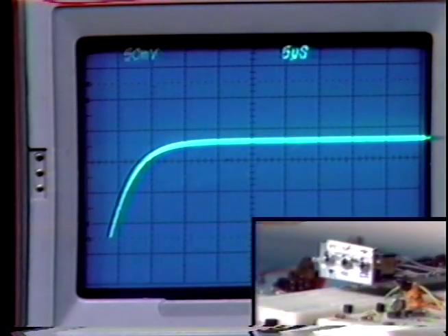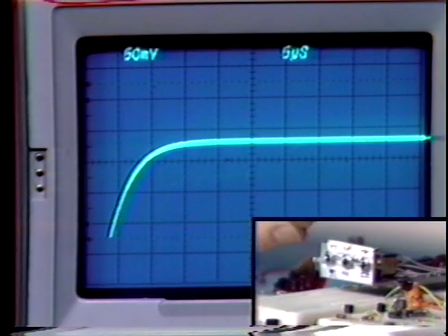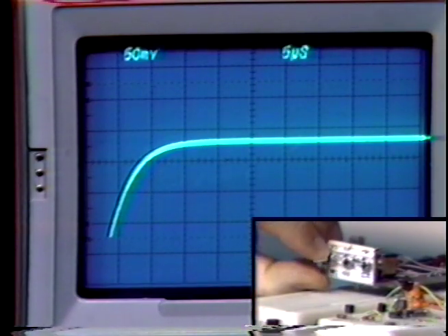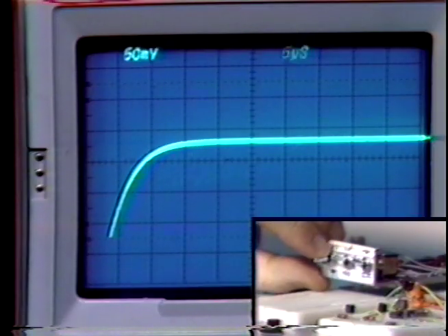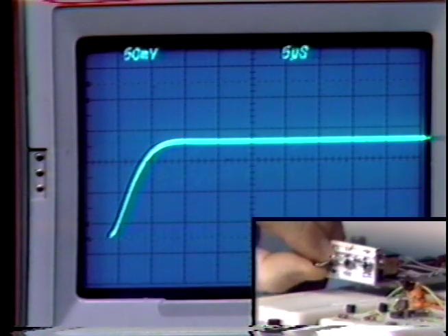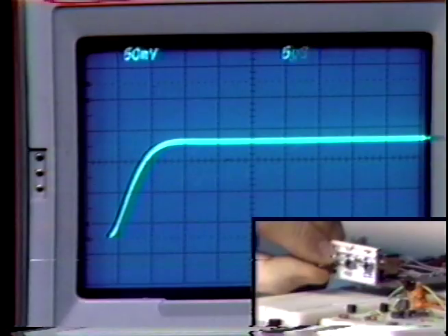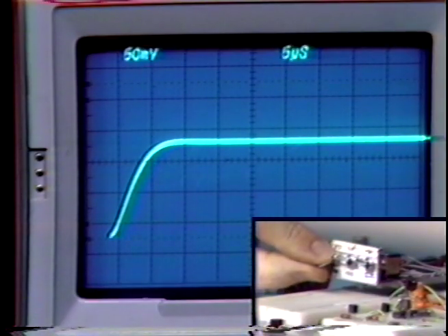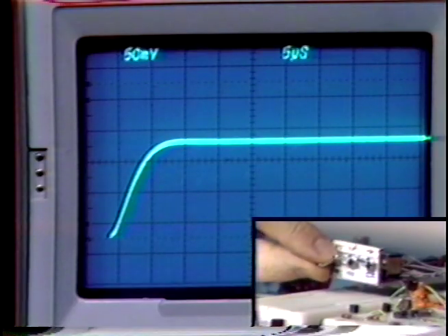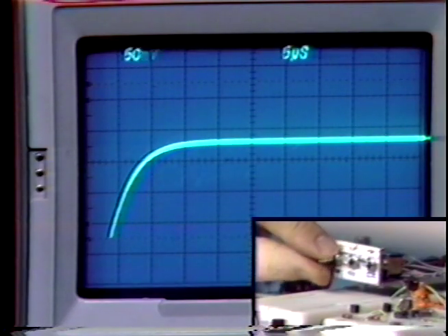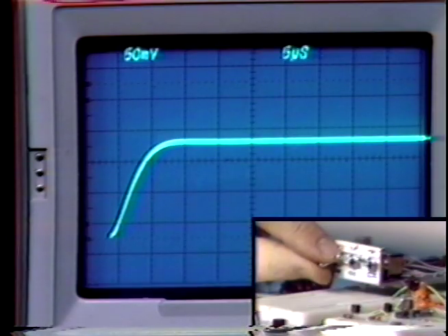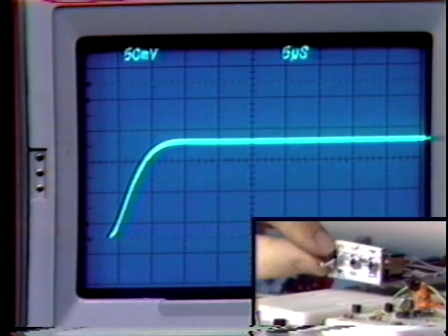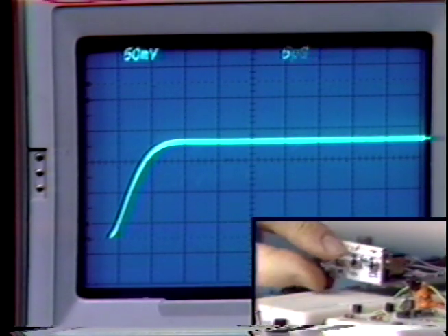Now let's begin to add additional poles. Let me start out putting in a pole at a megahertz. Well, that doesn't really have much effect on the response. So here's a pole going in at a megahertz. That's actually beyond crossover in this loop, and so there's very little change in the response. We see just a hint of overshoot, but really nothing very dramatic.